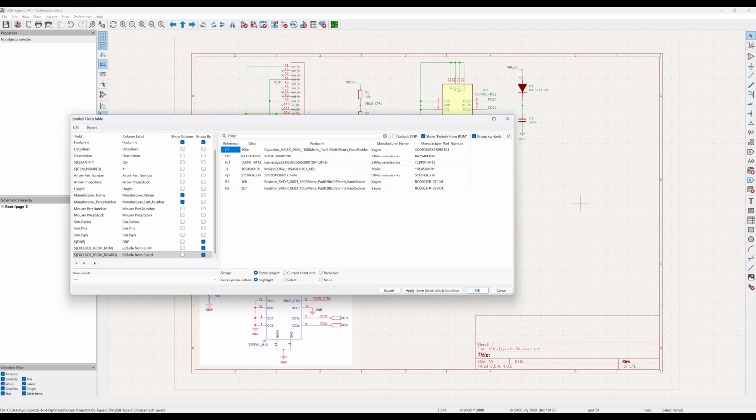For the resistors and capacitor I've selected 0603 package components with high stock availability from JLCPCB. Specifically, R1 is a Yageo RC0603FR0710KL, R2 is a Yageo RC0603FR072K7L, and C1 is a Yageo CC0603KRX7R9BB104. This update is made by filling in the manufacturer name and manufacturer part number fields in the symbol fields and then selecting an appropriate generic footprint, for example, a hand-solder 0603.